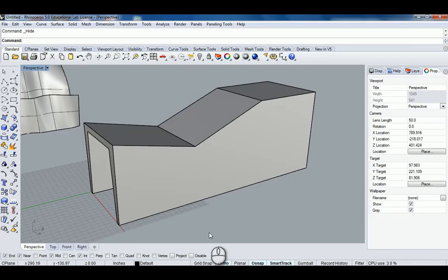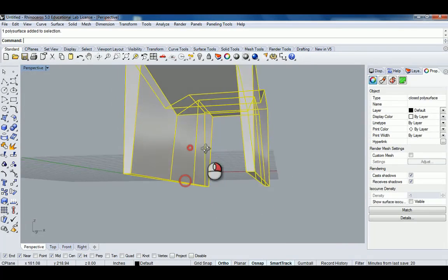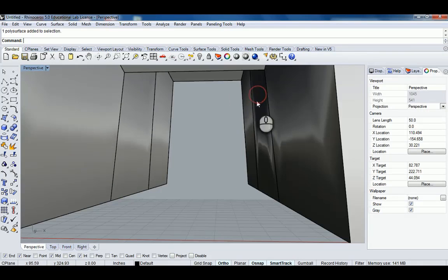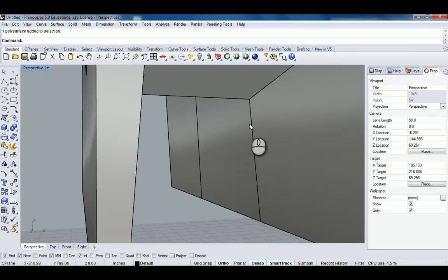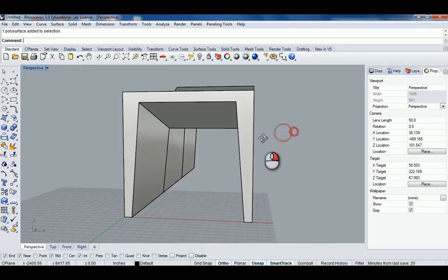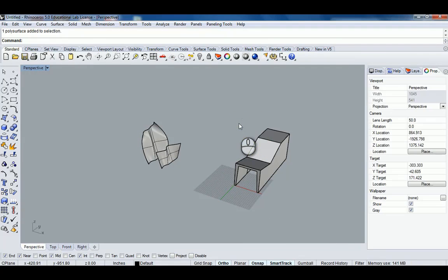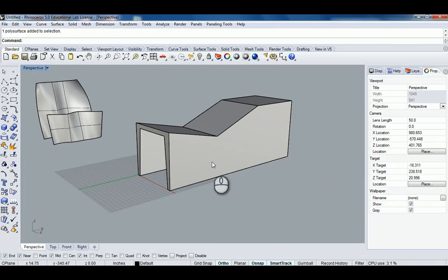It was seamed where the cross sections were. And it looks like it's still, because when I was adjusting the points on the inside, this line obviously is slightly askew of this line, so each of these actually are a different surface, technically. Anywhere there's a hard change, it's going to add a seam, basically. So the reason why we were able to simplify this outer surface is because even though there were lines that it used to create 3 separate ones, they're all coplanar. So whenever there's not coplanarity, it will create separate surfaces, basically.